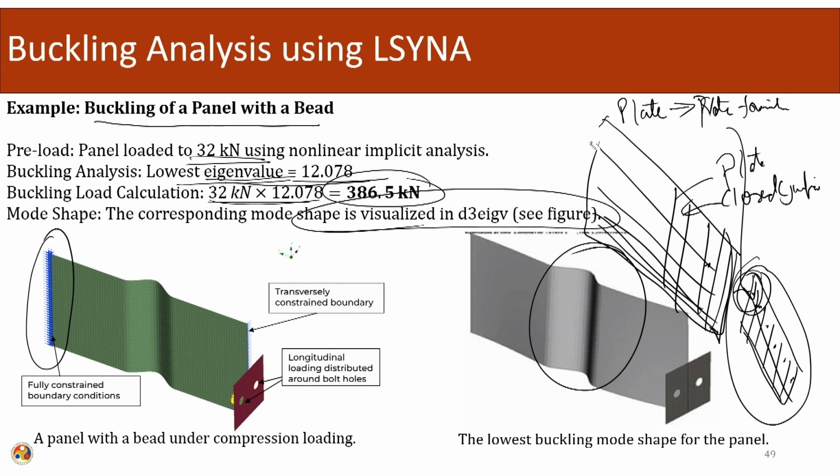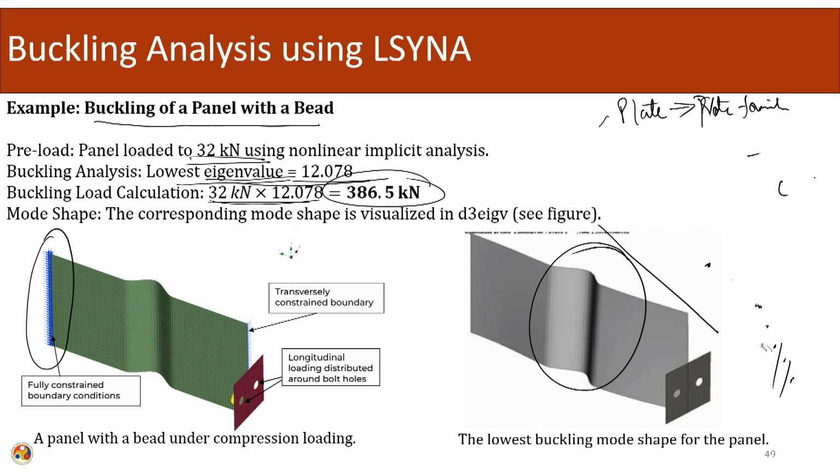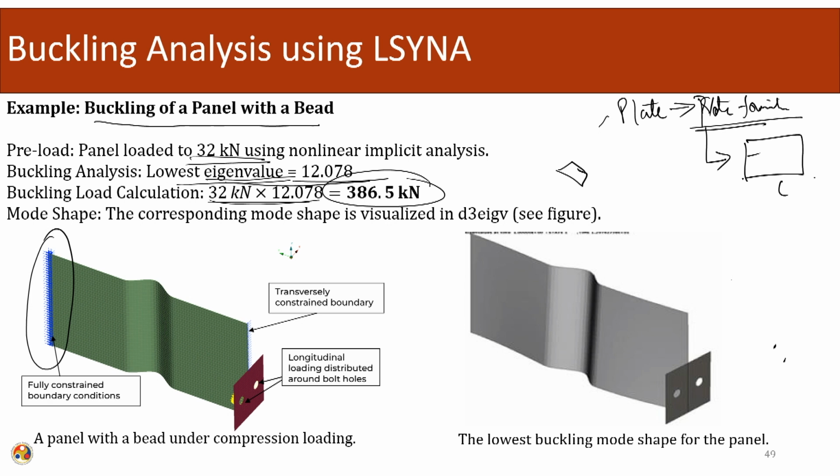After that, the longitudinal and the vertical directions are given. The only thing remaining is the thickness of the plate. In this plate formulation there will be a space where we need to specify the thickness of the plate. Depending upon the 2D problem or 3D problem, we can define the thickness. If it is a 2D problem, thickness is not required, but if it is a 3D problem, we need to define the thickness, as is given in the software. Sometimes in a 2D problem also we have the option of specifying the thickness of the system.